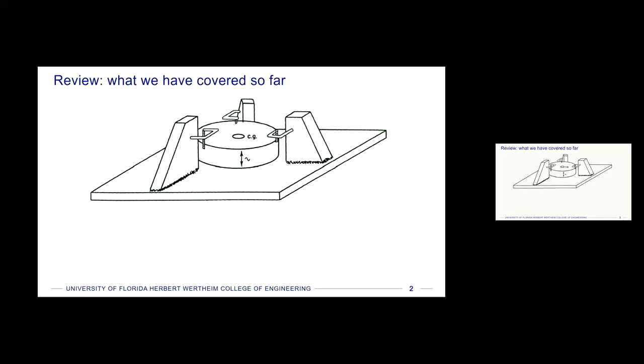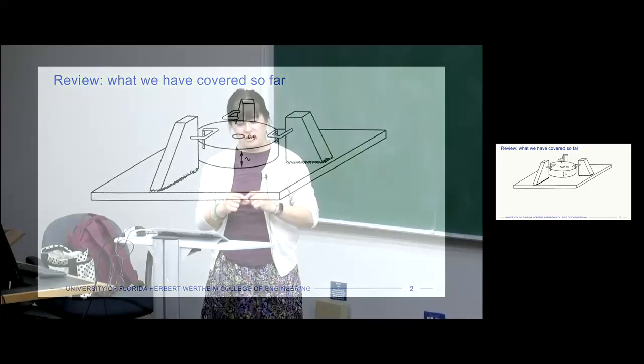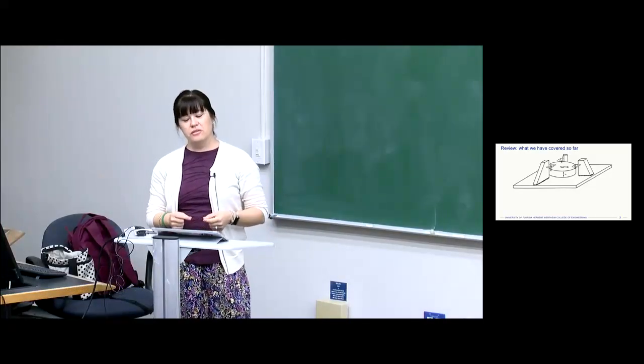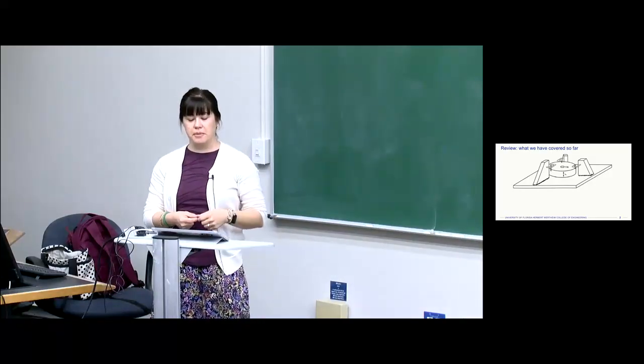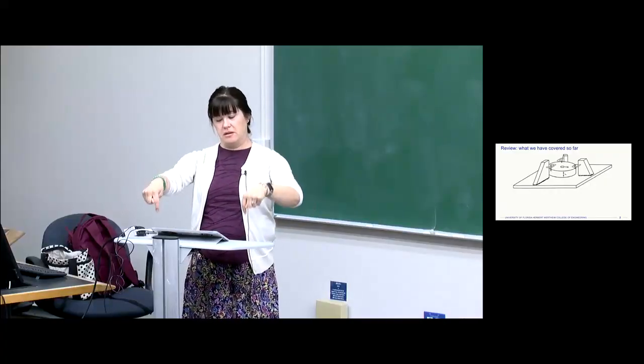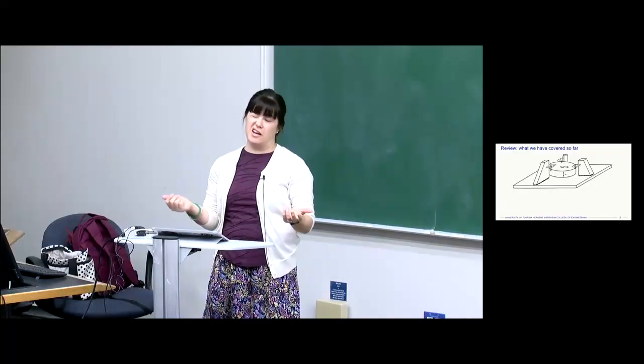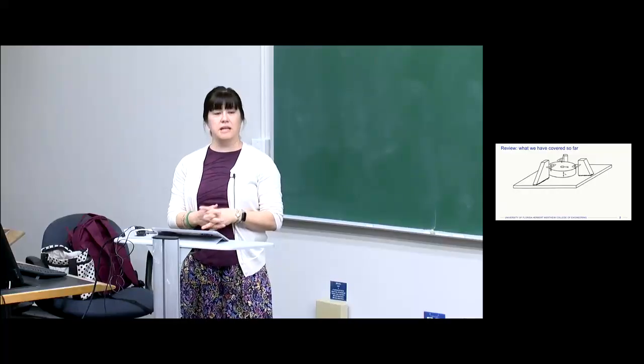Is it going to fail if we just load the mass on and leave it there, right? And so there should have been a fairly high safety factor to yielding. And the safety factor that you found, from what I saw when I was looking through all the assignments, depends on whether or not you considered the 3,000-pound mass to be distributed equally among all of those clips. If you distributed the 3,000-pound mass equally among all 3, then each clip had 1,000 pounds pulling down on it. And so you should have gotten a fairly high factor of safety on the static yielding.